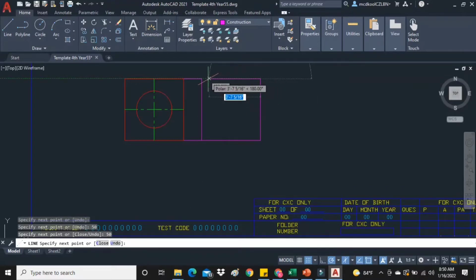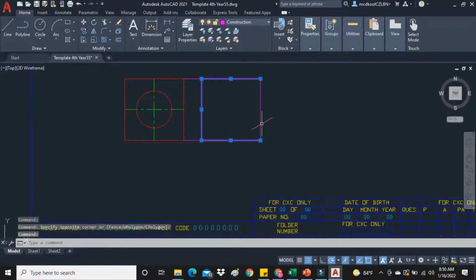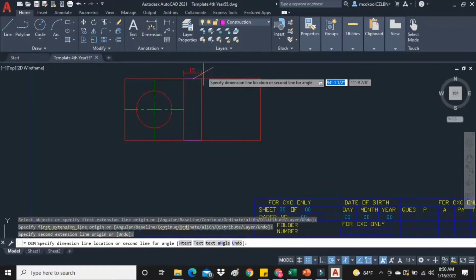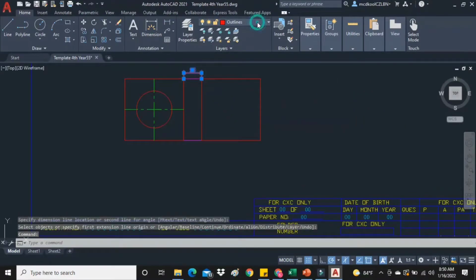And then I will connect it to the first part. So this here is the side of my drawing, the side of my block. So I'm going to make sure that I change these lines to outlines, which is the correct layer for them. Now, what I will do is I can check my dimensions here, make sure that the space between them is 15.